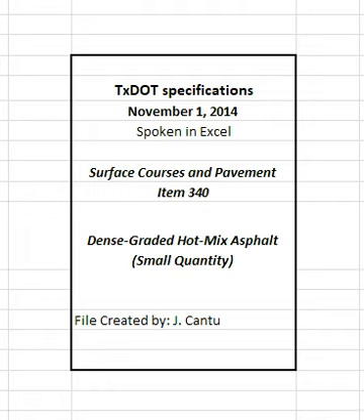Supply aggregates that meet the definitions in Tex 100E for crushed gravel or crushed stone. The engineer will designate the plant or the quarry as the sampling location. Provide samples from materials produced for the project. The engineer will establish the surface aggregate classification, SAC, and perform Los Angeles abrasion, magnesium sulfate soundness, and micro-Deval tests. Perform all other aggregate quality tests listed in Table 1. Document all test results on the mixture design report.